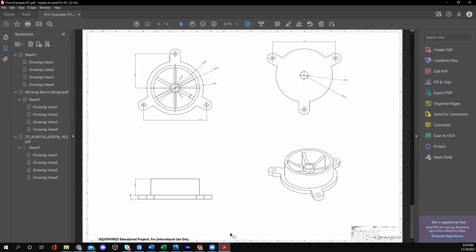So in that drawing that I made, not a great drawing after all, I gave you some dimensions here, but by far there's a few dimensions that are missing. So for this to be an inclusive blueprint, you would have to have a cross-sectional cut through, and that's how I would do it. I would cut it through one of these. I run my plane along the middle of one of these ribs, and then that way you could get all of those other heights.